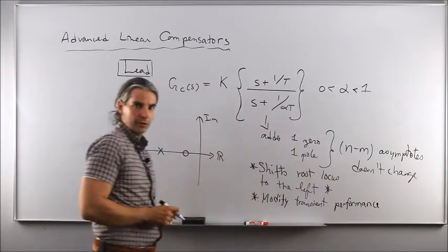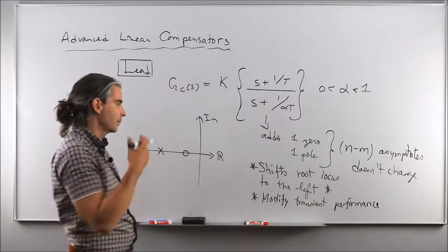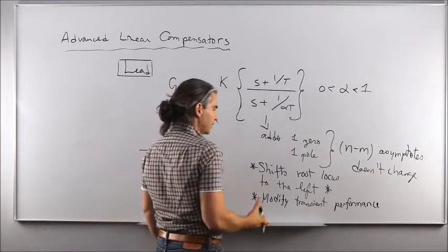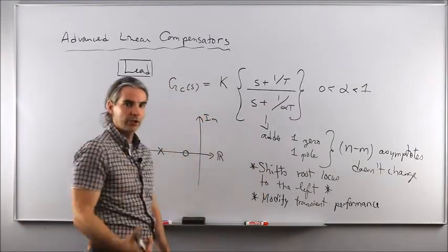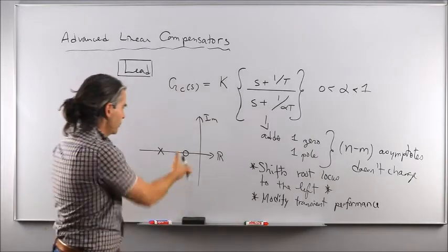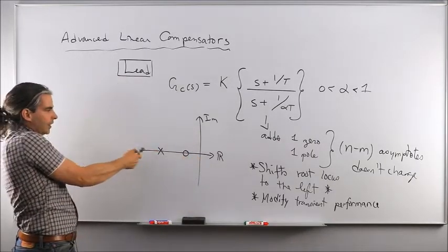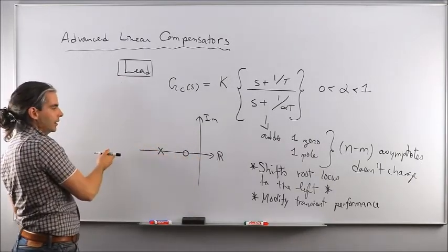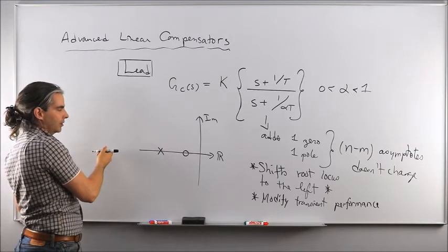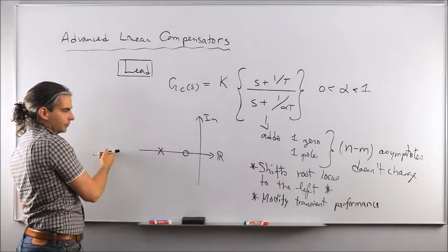Hopefully to the better. If you do the design right, you're going to improve the transient performance in terms of stabilization time, for example. Because you're going to pull everything further to the left, and the more you move in that direction, the lower the stabilization time becomes.